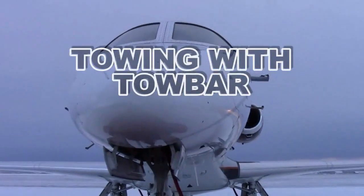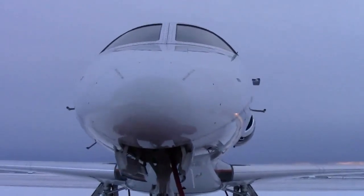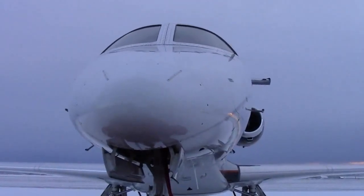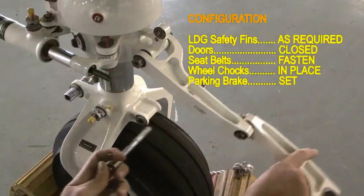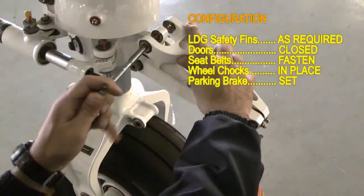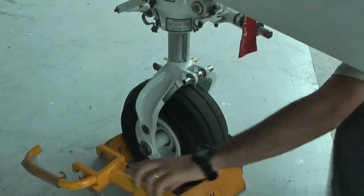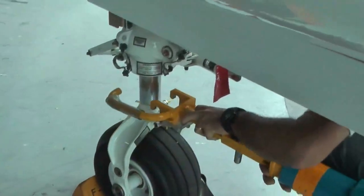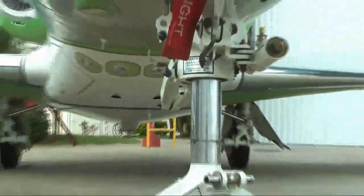Towing with Towbar. Make sure all ground equipment is removed from areas adjacent to the airplane and all external services are disconnected. Disconnect the nose landing gear torque link. Connect the tow bar on the nose landing gear. Connect the tow bar to the tractor.